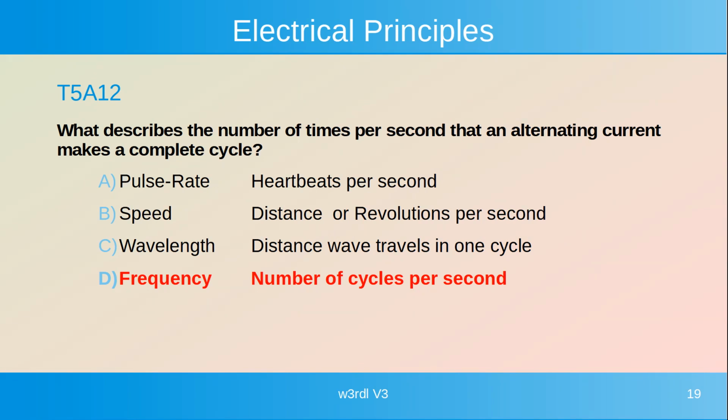Is that why the bands are called 10 meters, 6 meters? Yes, the physical length of the wavelength. Absolutely. And that's how antennas work. Depending on what frequency you're trying to resonate them for, they need to be a quarter or half wavelength.